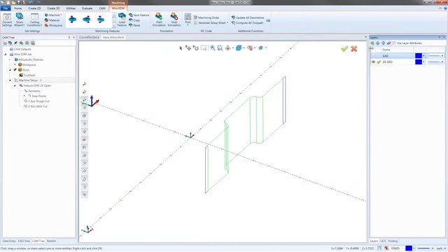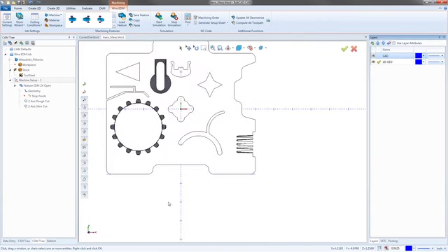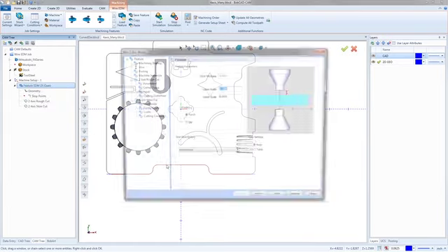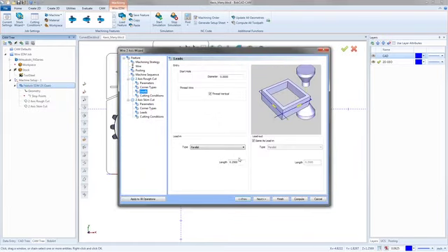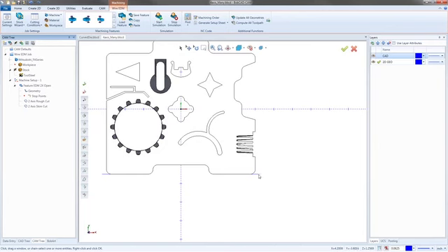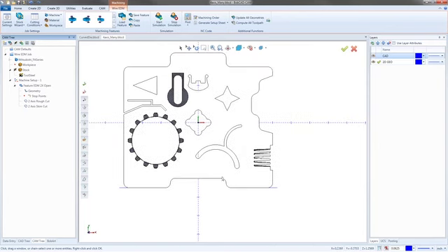And I think we'll be good with the leads. They're really close to the top of that. Yeah, we'll go bigger. Let's just go in. Let's edit this. Go to the leads page. And this is the best part. I make the change here. So I'll say a 1/2 inch. Apply to all operations. And that copies those settings over to here. So now I have both the same leads pages. So I can compute again. There we go. Now we should be a little bit further off that part. So now we have that one.